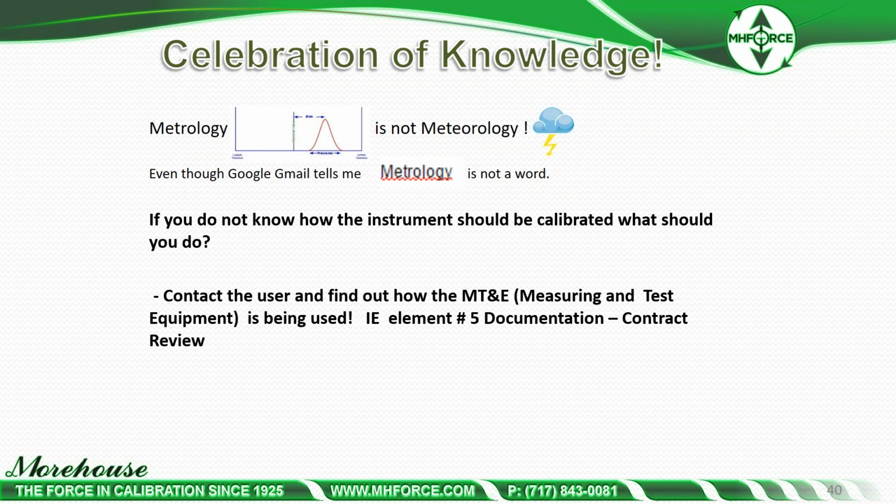Needs to happen. I know it's hard to get through purchasing in big companies, but you need to get to that end user. Otherwise, you could have a situation where you think the end user is using a device to 0.1% of full scale when someone used different pins and they're at 1.72%, and that's going to mess up every single measurement they do.